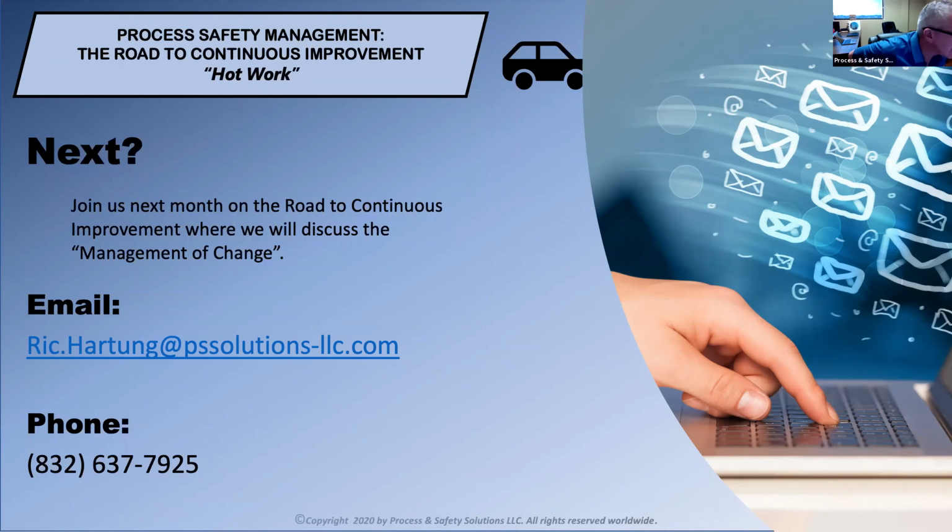The other question is, hypothetically, if a hot work is going to be done over the course of 3 days, is it compliant to document the hot work permit for 72 hours instead of 1 for each day? Typically, that is not done. Typically, a hot work permit is good for 1 shift period. So whether your shift is 12 or 8 hours, issue a new hot work permit, because things change during that period of time. Again, it goes back to you developing your policy and procedures on how you're going to apply hot work in your facilities.